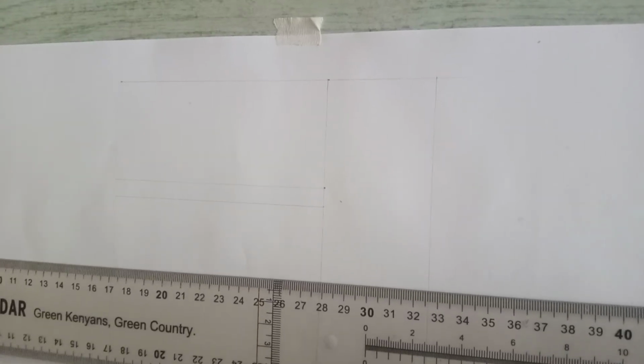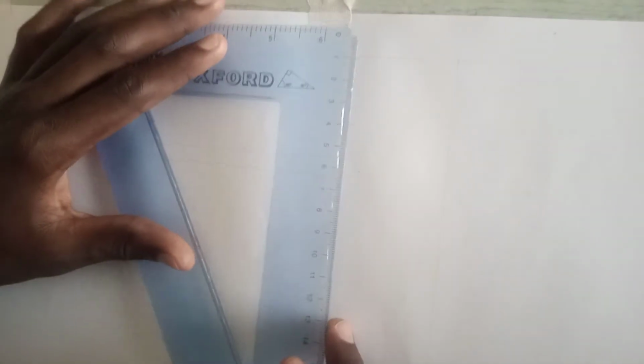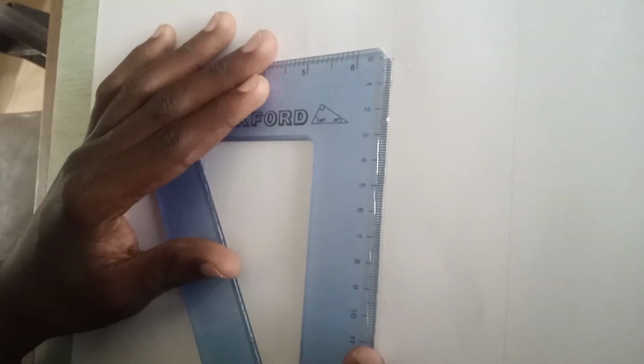And the width for the second flight is also 1200 millimeters. So that implies that they have the same dimensions. So we can just transfer the same 48 millimeters to this other side. 48 millimeters down here.